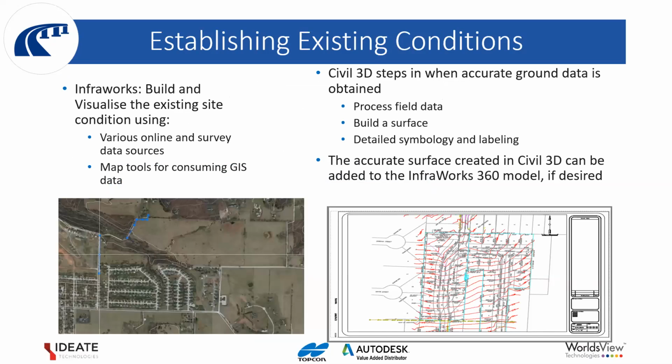So of course, as you know, you can't design this geometry anywhere or out of nothing. The first thing you usually require is to establish the existing condition in terms of the topography, the existing buildings, the existing roads, and existing utilities within the project area where the new project is going to be done. You can still do that within Infraworks by building up from different data sources, like maybe photogrammetry, point clouds, LandXML, and all those different file formats. You can use them to build up your site in Infraworks, then develop your context, do the concept, and do the preliminary design, as I will illustrate.